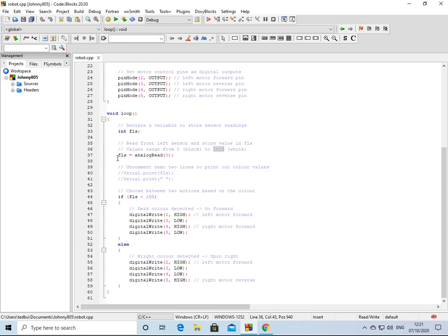It can't differentiate between different colors like red, blue and green. It's only able to see how bright the color is. So you just get a number between 0 and 1023, and that's all the robot sees, but it sees it under each of its four corners, and then it has to make a decision about what to do with the motors based on those readings.